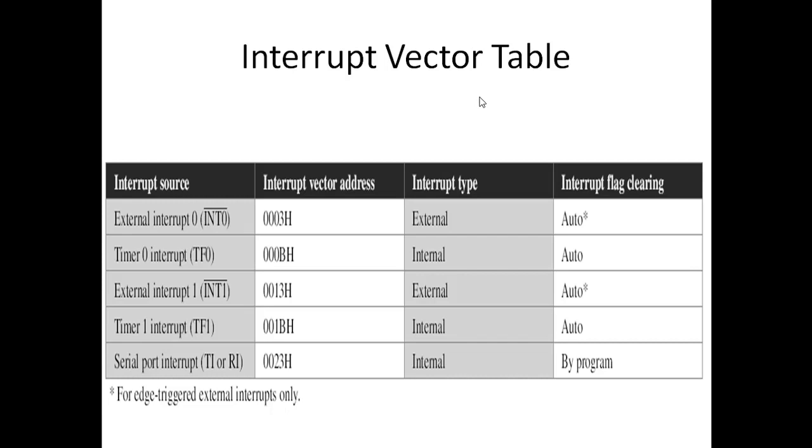Okay, so let's get a concept of what happens. Suppose an event occurs outside and my peripheral wants to inform my microcontroller that the event has occurred, and it sends that signal on the external interrupt pin INT0. So as soon as my microcontroller receives this external interrupt, what will happen? Think about everything properly, right? It will suspend the execution of the current program and provide service to external interrupt 0. Now what task has to be done?